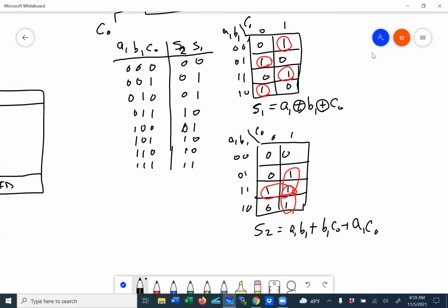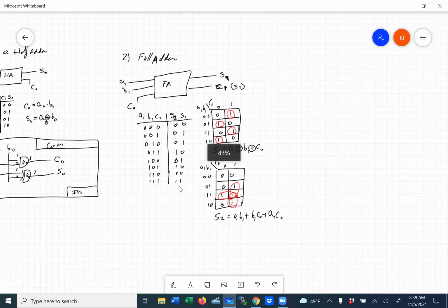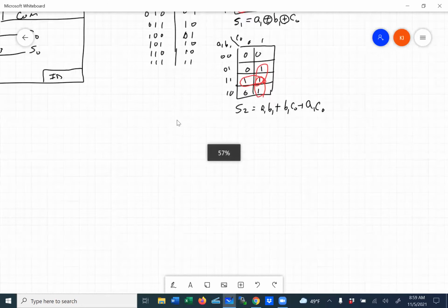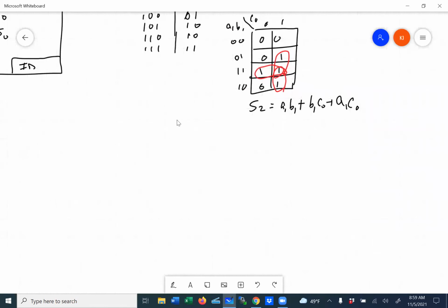So now for a full adder, we've got to do the schematic to be complete, so if somebody wants to use it, they know how to use it. So what we're going to do is do the same thing. Notice for these, you don't need to use the switches because you're implementing a module that's going to get plugged into your full design. You're not going to implement them by themselves, so you don't have to do the switches in here if you're wondering. So here, the inputs to the system, and inputs always come in on the left-hand side of your schematic.